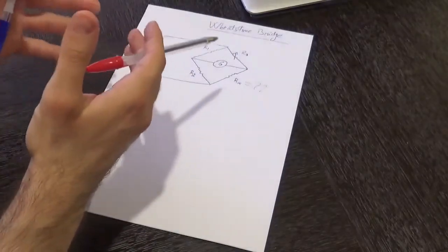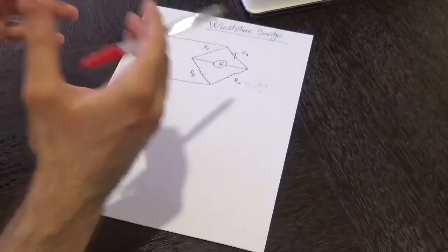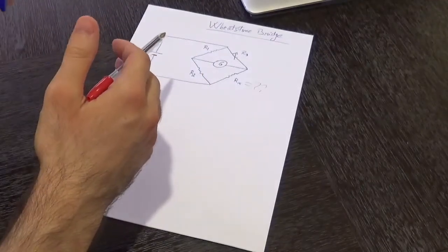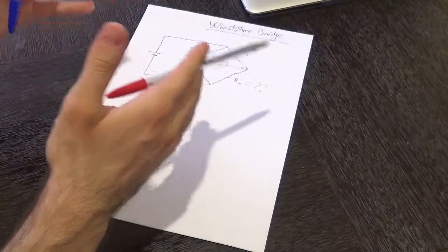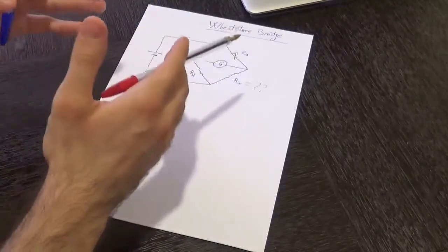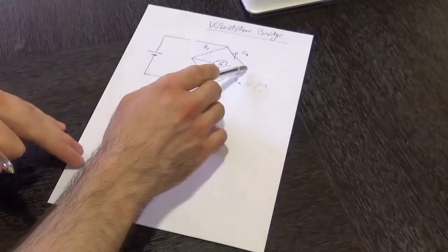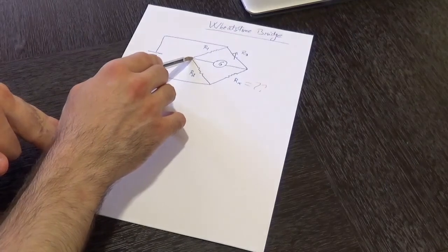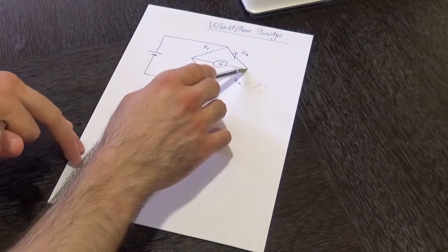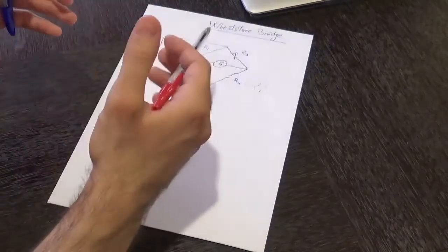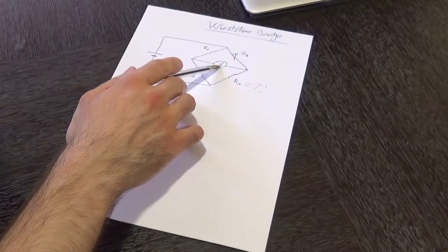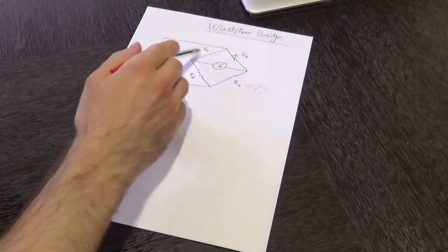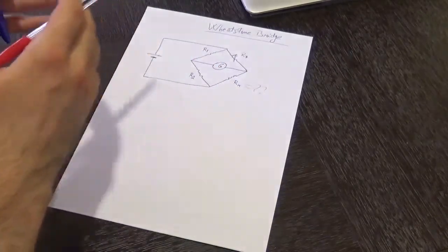But what do we actually mean when we say that we need to balance out two parts of a bridge circuit? We know that the electrical current in a circuit flows from a high potential point to a low potential point. So when we say that the Wheatstone bridge is balanced, it means that the potential at that point is actually equal to the potential at the opposite point. Therefore, the potential over here is equal to the potential over there, and in that case, the potential difference between them is going to be zero. Therefore, the galvanometer would be reading zero value for the potential difference. And in that case, these two parts of the bridge circuit are labeled as balanced.